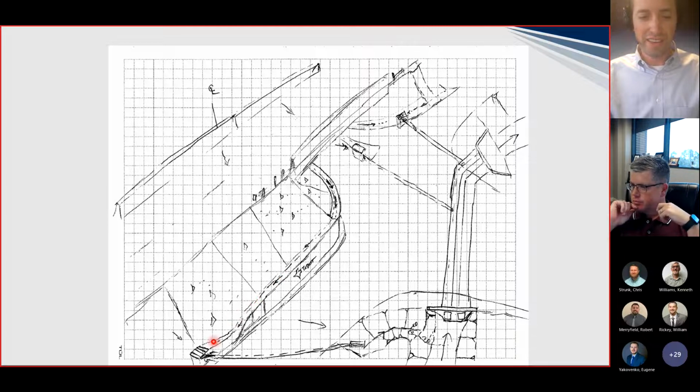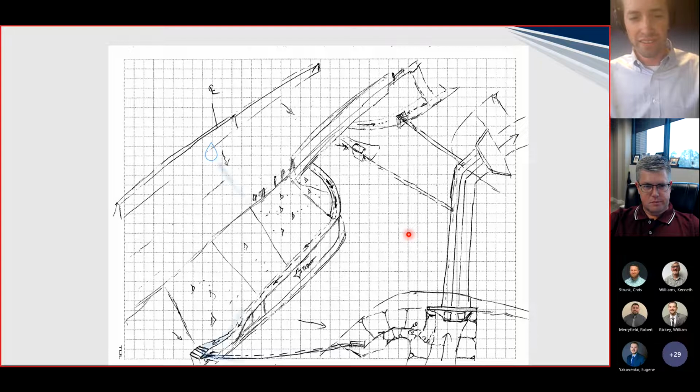Then we might consider that we don't want the water just sheet flowing across the roadway because it's going to be a little bit concentrated. So we need to depress it a little more, put an inlet there, and drain under a pipe. We need to have enough cover under the roadway to put a pipe and go into this ditch. And then, of course, we have the cross culvert sizing for a major structure like this. So if a drop of water falls right here, it's going to take a path like that.